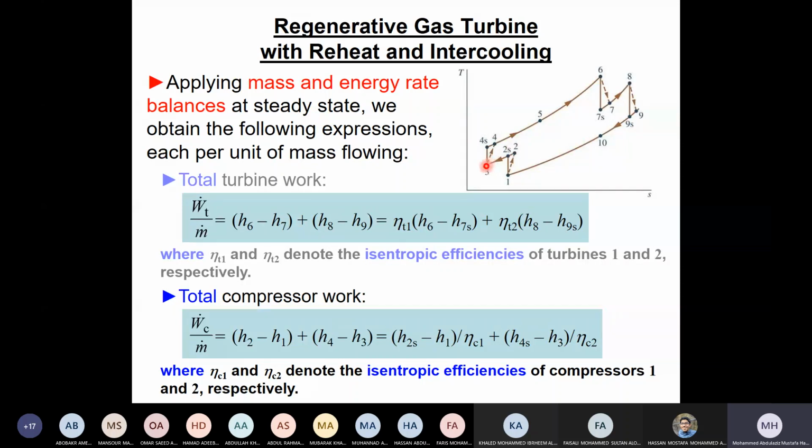Then I do the same here, going isentropically up to this pressure. This pressure will be given in the problem. So now I have 4S. Then the efficiency will be given, so I divide and get T4. So now I have 4 and 3, therefore I can say Cp (T4 minus T3), and then I calculate the compression work, all of it now.